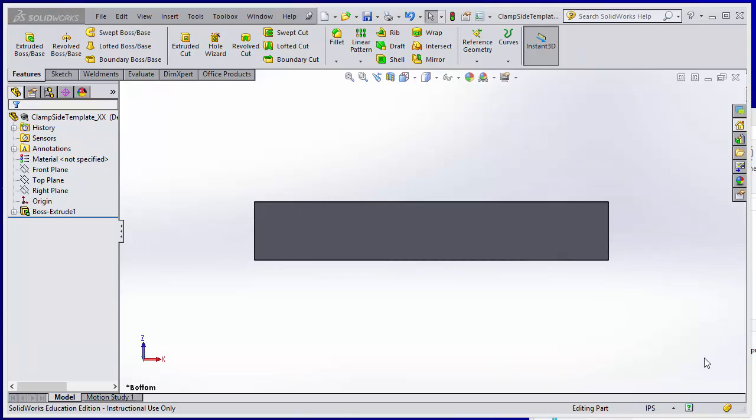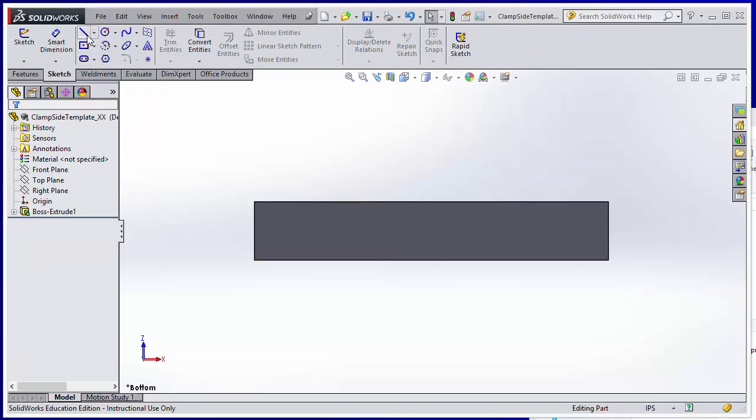One way to create an angled cut is to create a line here from one vertex to the opposite side, and then we'll specify the angle. To do this, first we'll need to sketch a line. So we'll switch back to the sketch tool set, and then I will select the line tool, which is directly above the center rectangle tool you used to create your initial sketch.